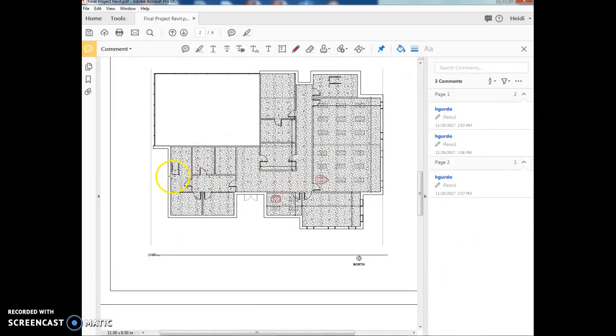The other thing is your floor is going through your stairs right now, so you want to go back into your textbook and look at how to make the floor go around the stair shaft. So that's also going to be in lesson 6. You'll see that the floor, if I was to look at the floor outline, it should run something like this, where it goes around the whole perimeter of the building this way.